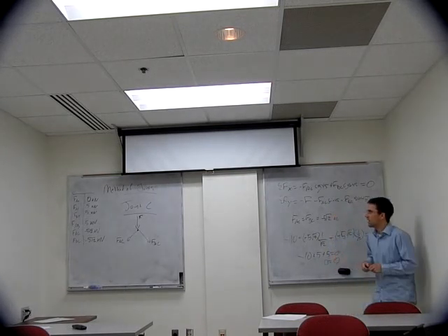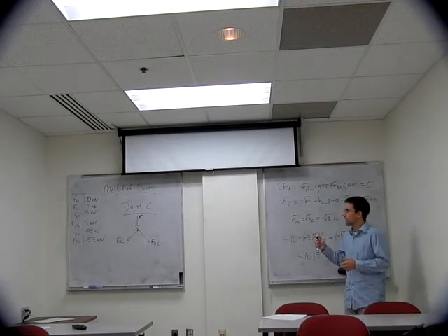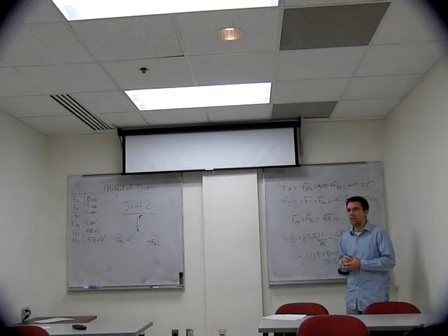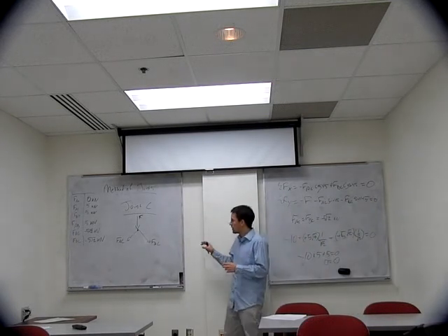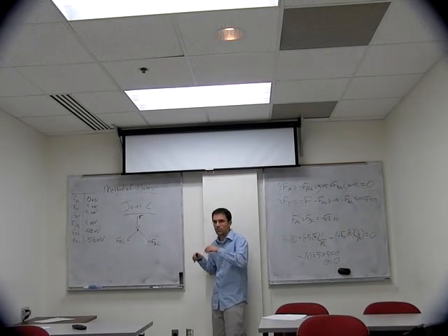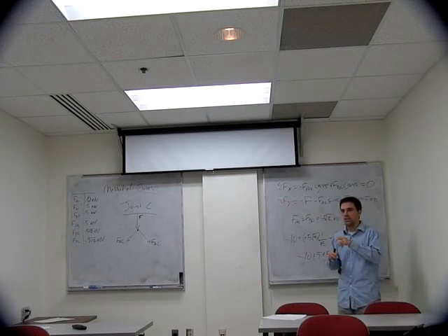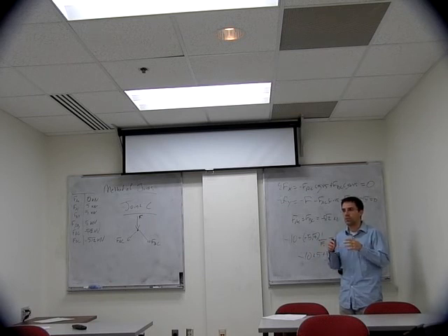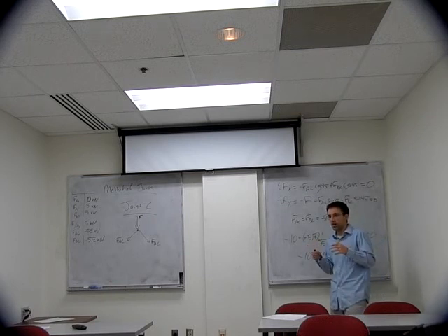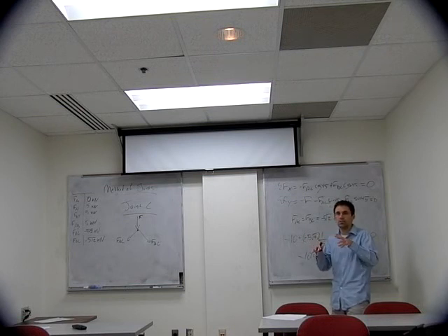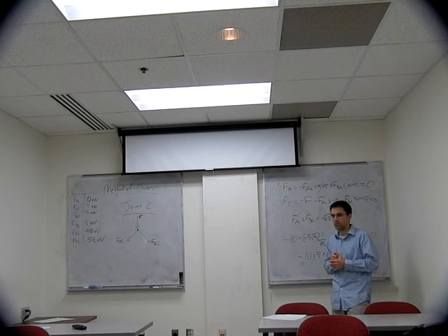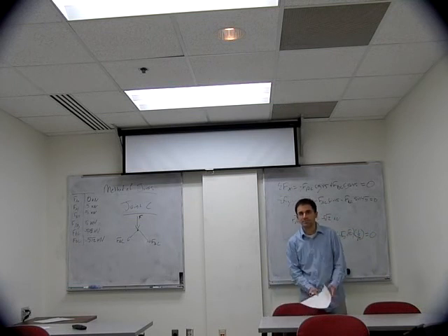All right. And next class when we come back, we'll start looking at what's called the method of sections. Instead of here where we only looked at the joints throughout the truss, the method of sections allows you to look at just specific areas within a truss, and that can be useful in a large system where you have many joints and you're only interested in the forces in a specific area. So it allows you to reduce some of the analysis that is required.